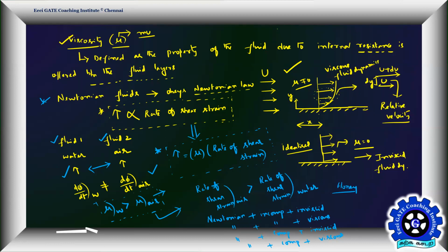Next problem. You want to think about viscosity. So therefore viscous, Newtonian, but you are not going to talk about a fluid where tau is not proportional to rate of shear strain. So for Newtonian plus incompressible, density effects you are going to neglect. Next one, inviscid, no need of Newtonian, just leave that. But compressible, you want to see density effects. The last, a very complex problem, density changes, and it's highly viscous. Are you guys clear? Everybody? Any questions here? Any doubt?